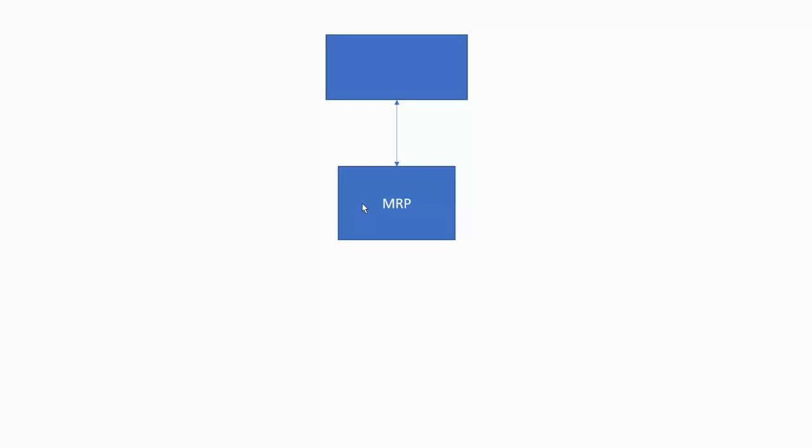For example, if 10 mm bar is not available, then what do you have to do? You have to go for the higher side, that is 12 mm, and then do the turning operation. So you have to procure material of diameter 12 mm. Then before procurement, you have to check inventory once again, like how much stock you have in hand initially.